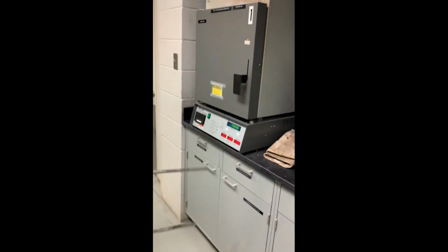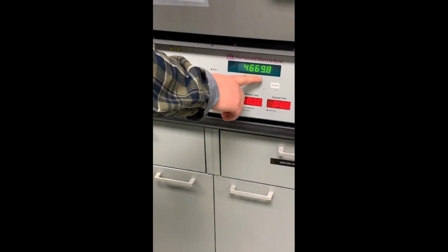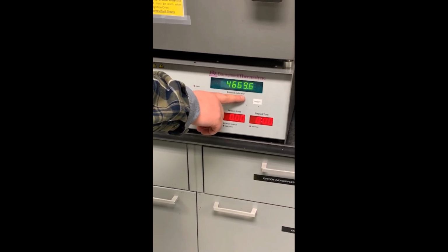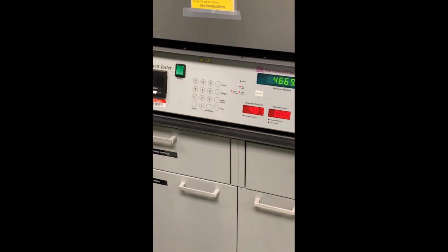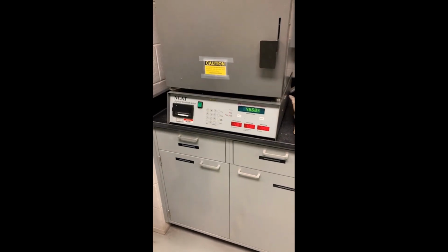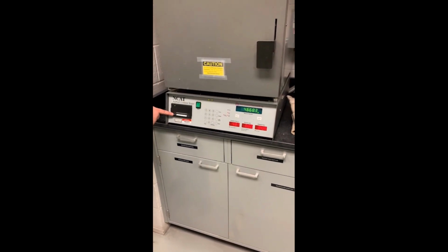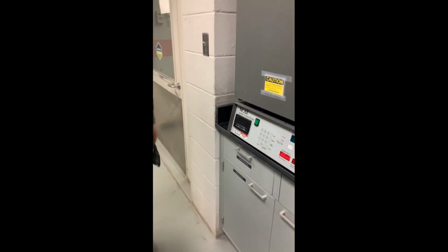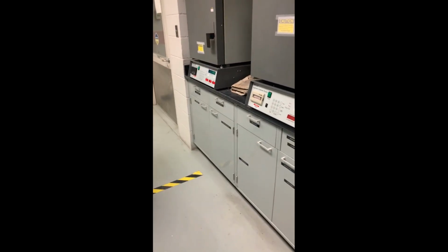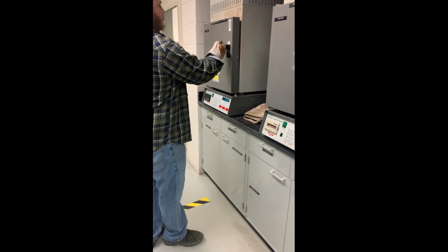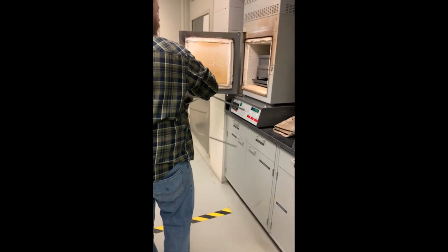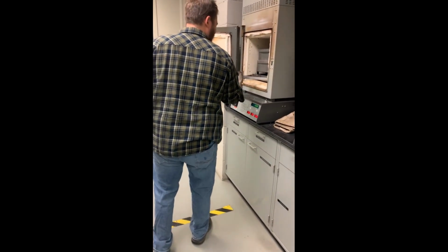Close the door and then wait for the scale to even out, making sure it's within 5 grams of the total basket and sample weight. Then you can start by hitting start. Make sure the door is locked and that the sample receipt is starting to print. After it is done, remove the receipt with the sample information. Hit the stop button to unlock the door, and then remove the sample.